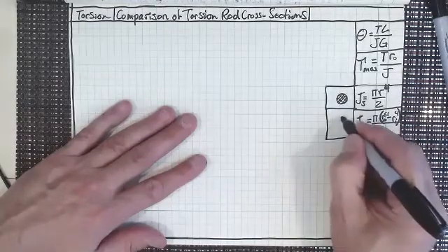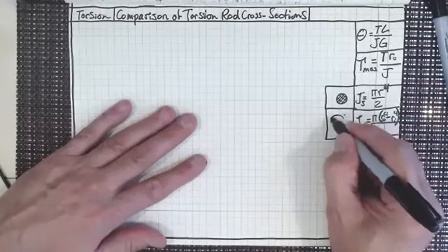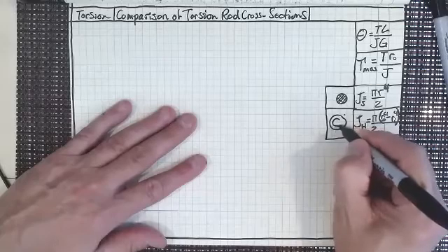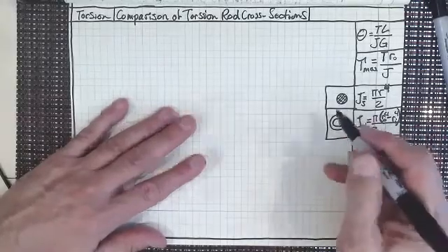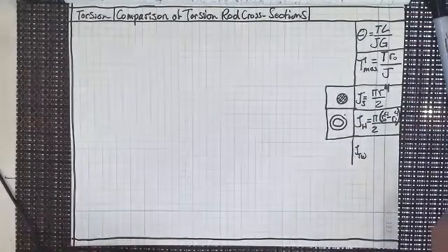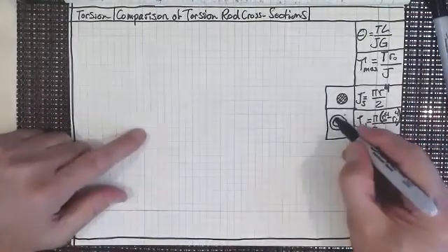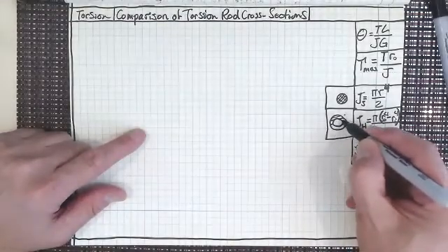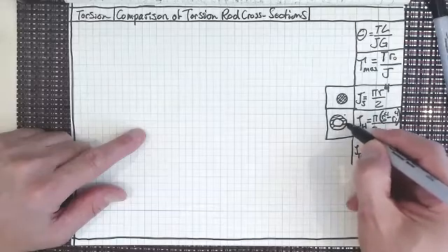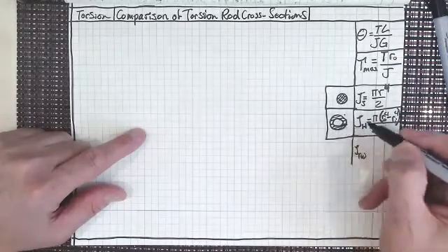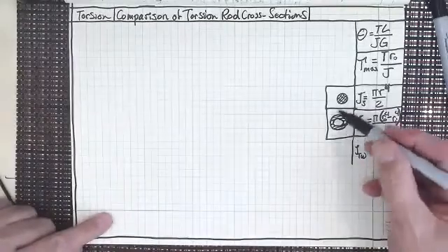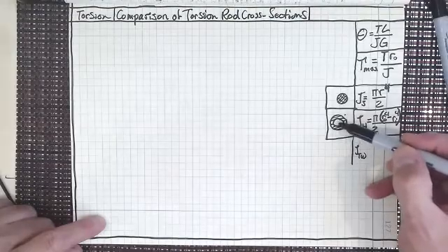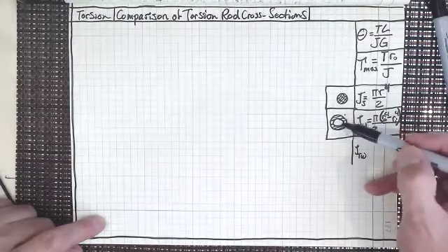But usually when we're looking at a hollow torsion rod, we're usually looking at about 80% of the core being cut out. And so what's left of the cross section, I guess I can do this in black, is the other 20% of the radius that we still have. So when I look at a hollow cross section, I'm assuming that the bore that's been cut out, now here you can see it's probably about 60% or 50%, but I look at it as being about 80%.